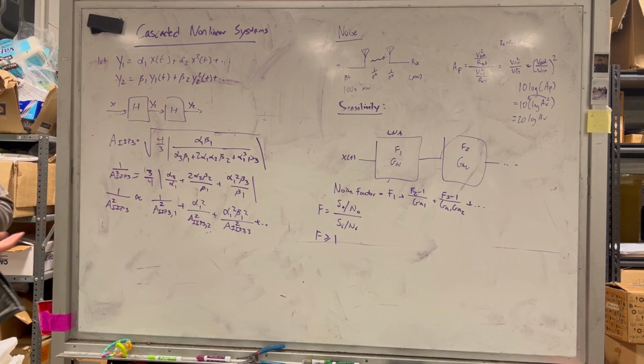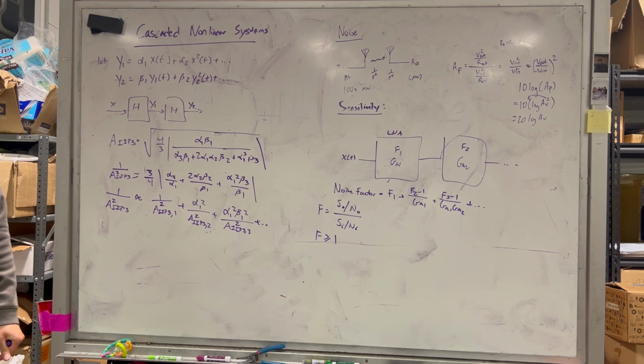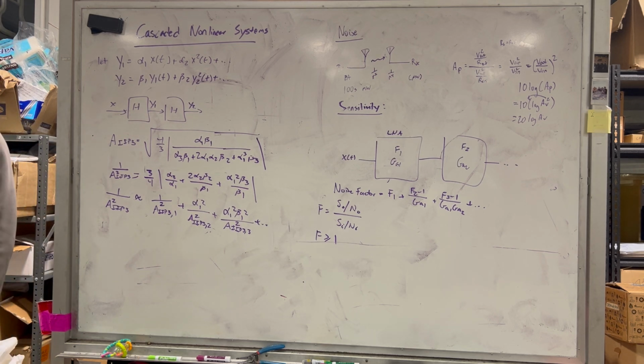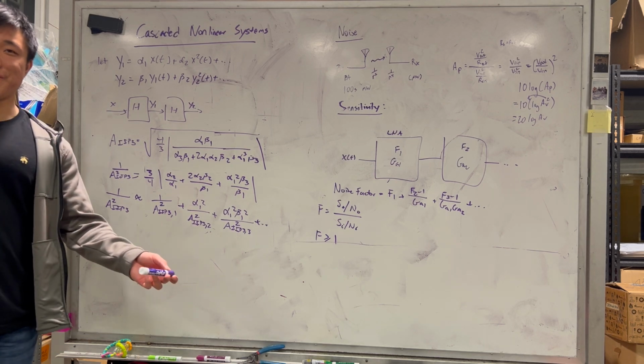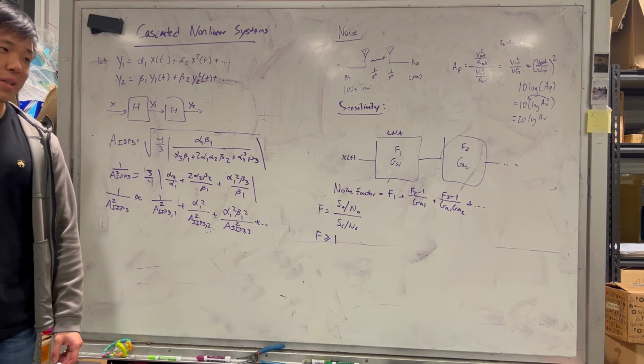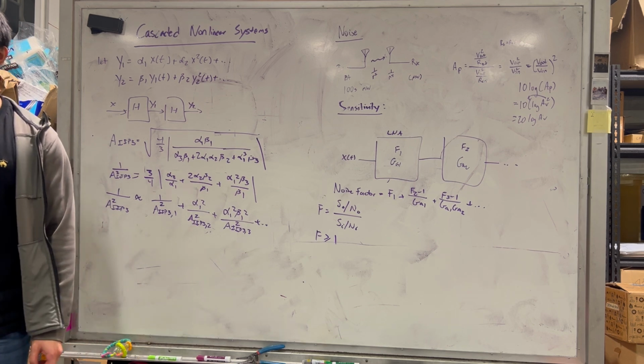So that's essentially what I want to go over today. It's just the high level overview of everything. Now hopefully the reason why you can't have super large gain in a common emitter amplifier makes sense. Even if you bias everything correctly, when you have a really large swing, you're going to see all those effects that I talked about.